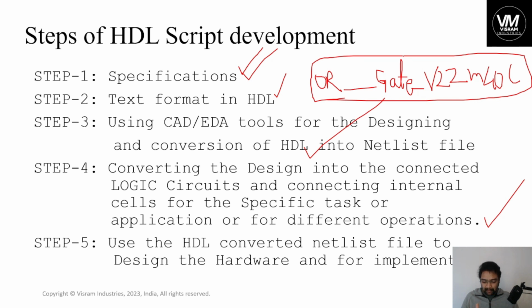Synthesis is nothing but a process of converting the hardware description language into the gate level netlist. Gate level netlist is nothing but all the logic cells. You won't be doing it only for an OR logic gate; it will be done for all the logic cells that you have written in the HDL code, in the complex HDL code, where you are using the processor, counter, clock wizard, and system debug, and also address protocols.